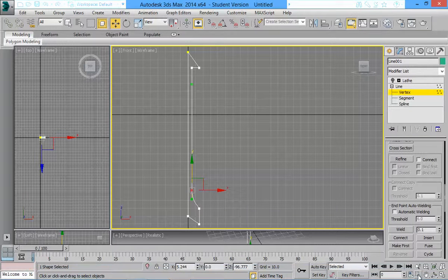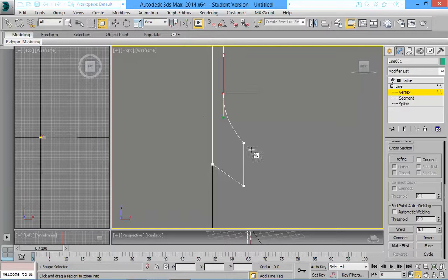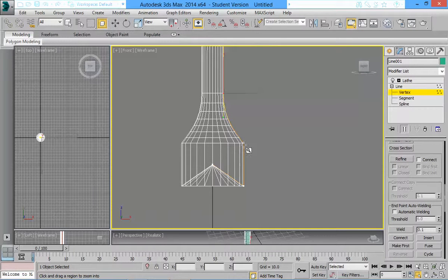Now just understand what is happening here. You see from here to here there's a straight line. Here to here also I got 2 points, but it's not a straight line. I've got a curve here determined by the Bezier, but when I lathe it, see how many points I have from here to here. 1, 2, 3, 4, 5, 6. 6 in betweens. From here to here, because it's a straight line, I don't need to put points to make it count, but here I get 6 more.